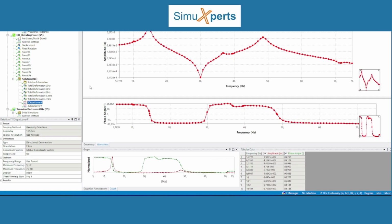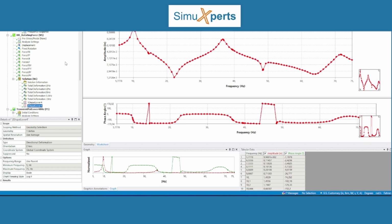This is for the vertical displacement, so the Y direction displacement at the node where the loads are applied. So that's vertical, and that's Z direction, or transverse. And what we clearly see here is the amplitude of that node with respect to the different frequencies at which we solved. So we asked for a solution that goes from 5 to 75 Hertz. That's why the x-axis of that plot goes from 5 to 75. And we clearly see the response.